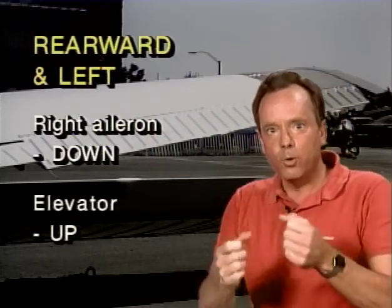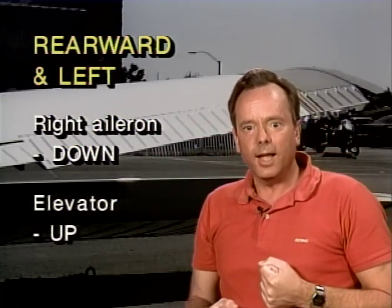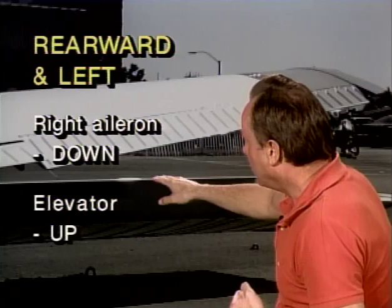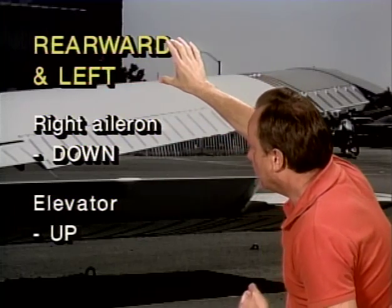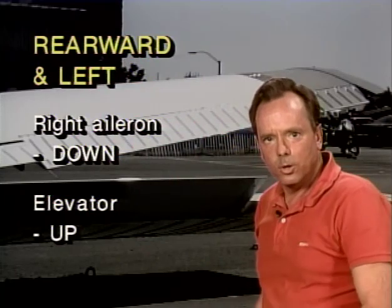The right aileron will go down. And if you move the wheel back, that means you're trying to make the airplane climb, and that means the elevator will go up. So if you move the wheel or stick rearward and to the left, the right aileron is going to go down and the elevator will go up.